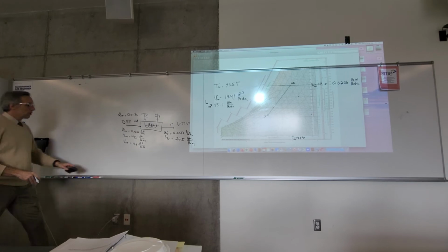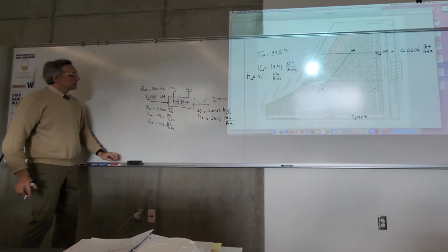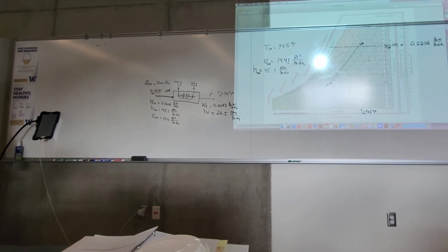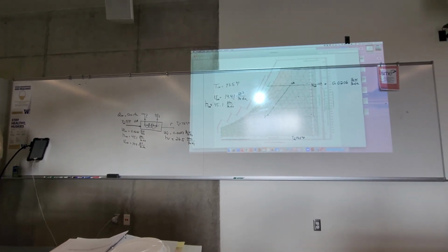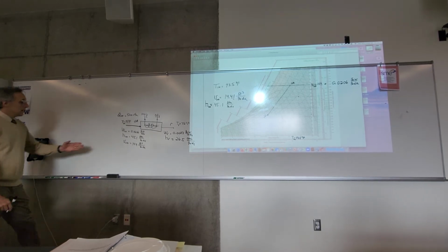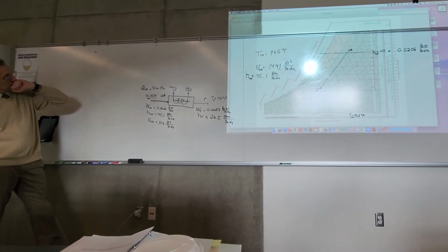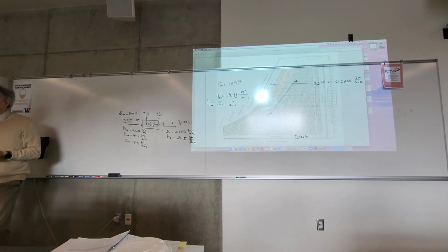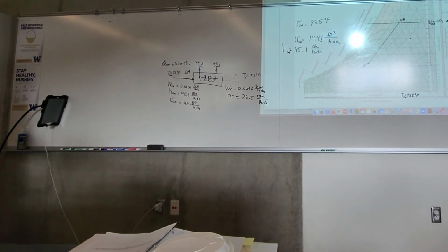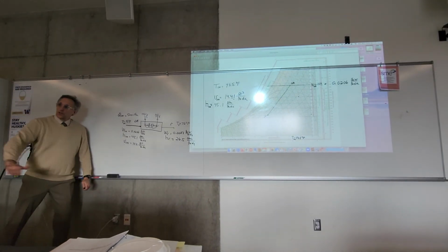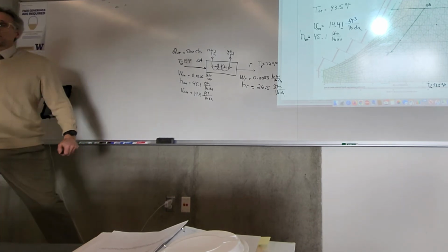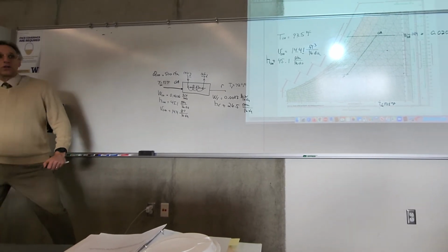This comes close to maybe a car air conditioner, but even a car air conditioner is going to have some mix of outdoor air and air from the compartment, although you can adjust that so it's only outdoor air coming in. And there are specialized air conditioners called dedicated outdoor air systems, or DOAS, that don't have any return air. All the return air is exhausted, so it's a once through. You push the air into the space, and then it's sucked out and exhausted and replaced with all outside air.